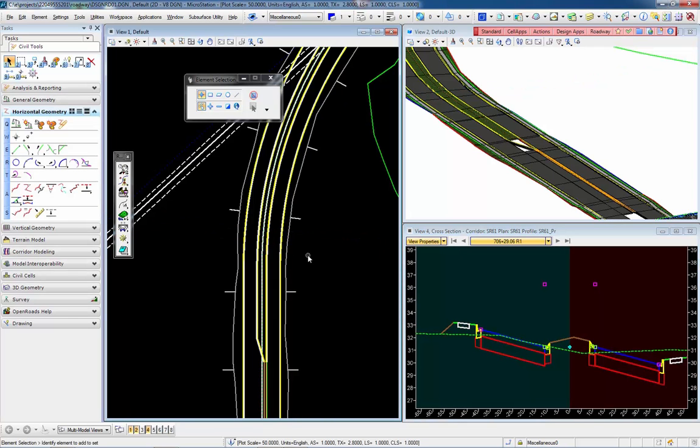Now, the first things that you're going to need for the gen files, there are three things. You'll need the top surface of the proposed design, the bottom surface of the proposed design, and then the existing ground line. And those will need to be provided in cross sections. So in order to accommodate that, there are other design stages that are provided in FDOTSS4.